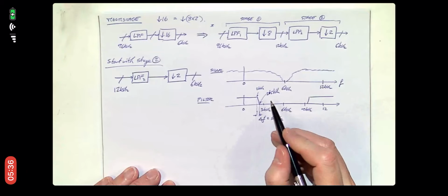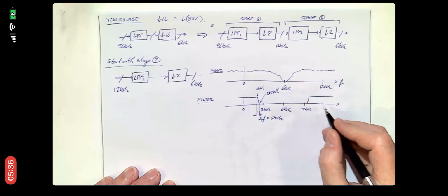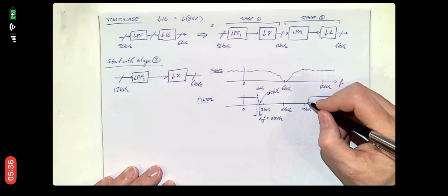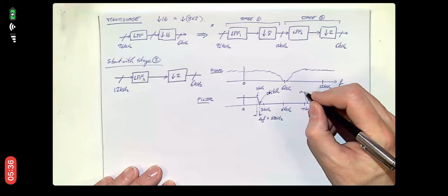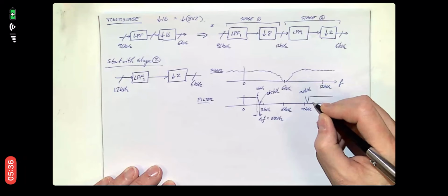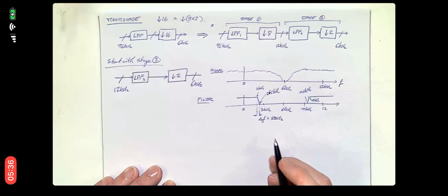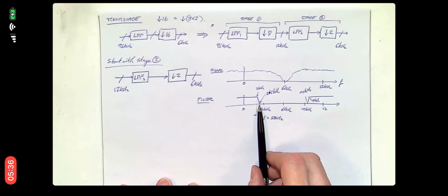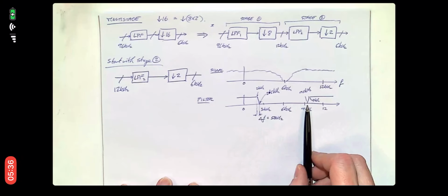We've also got, 2.5 kilohertz is down here, so up here, this point is 9.5 kilohertz. Up here with 9 kilohertz at the top of the filter there. So what we can see here is that the filter that we're going to design will chop out everything between 2.5 and 9.5 kilohertz.